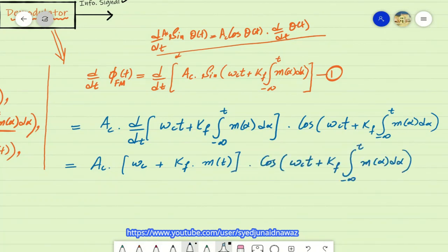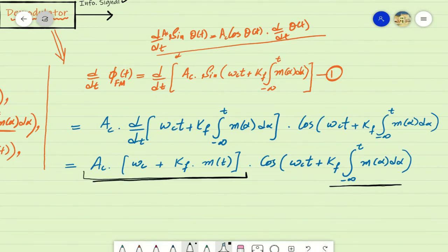So after taking the derivative of the frequency modulated signal which was received at the receiver, we obtain a signal which has representation of the information signal on its phases and frequencies, as well as the information signal influencing the peak amplitudes of this signal. So we have the information signal's representation both in phases and in amplitudes of this signal.